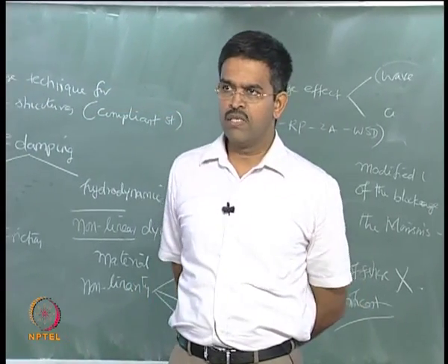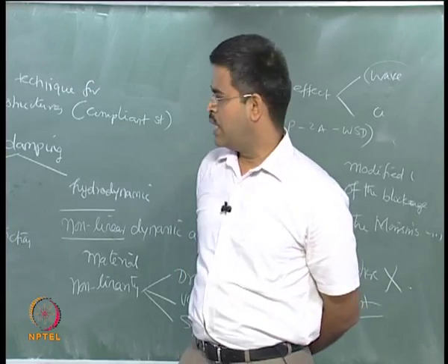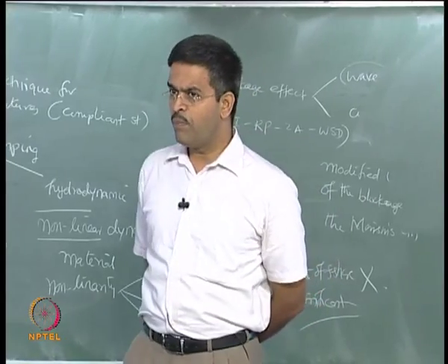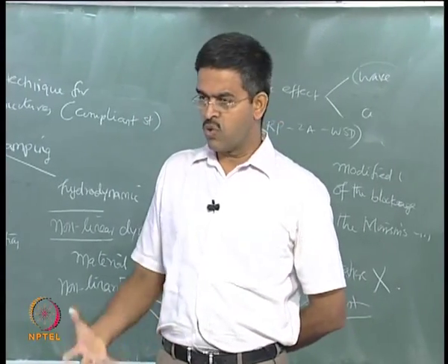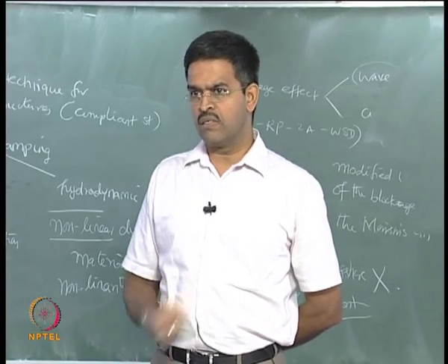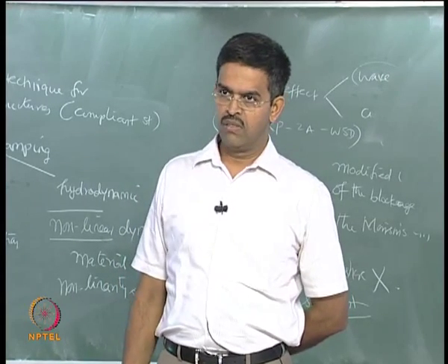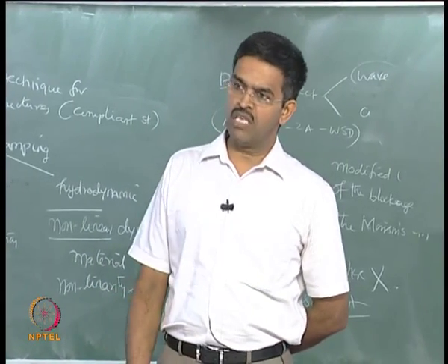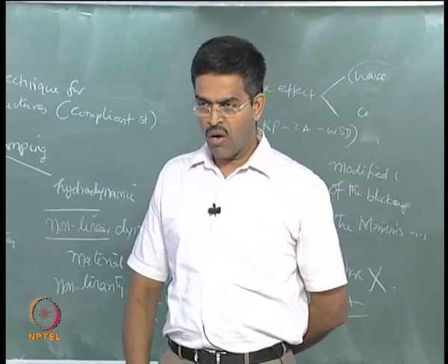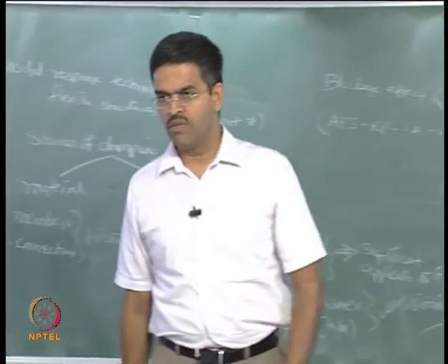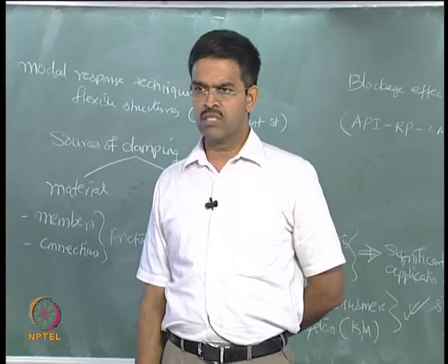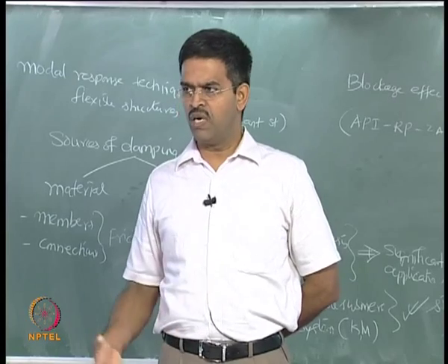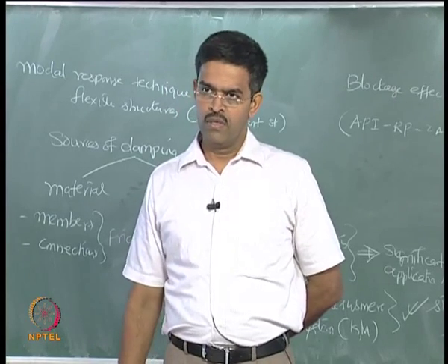So in this lecture we have quickly seen how the interface between the fluid and the wave, or the fluid and the structure, will impart additional forces in terms of force magnitude, frequency content, energy presence, orientation of the cylinder, length of the cylinder, then how the flow field is altered significantly where the drag forces or the lift forces will occur at a specific frequency which otherwise does not get reported, how vortex shedding frequencies will activate the response of the structure when it is being interfered with the wave or with the fluid flow.